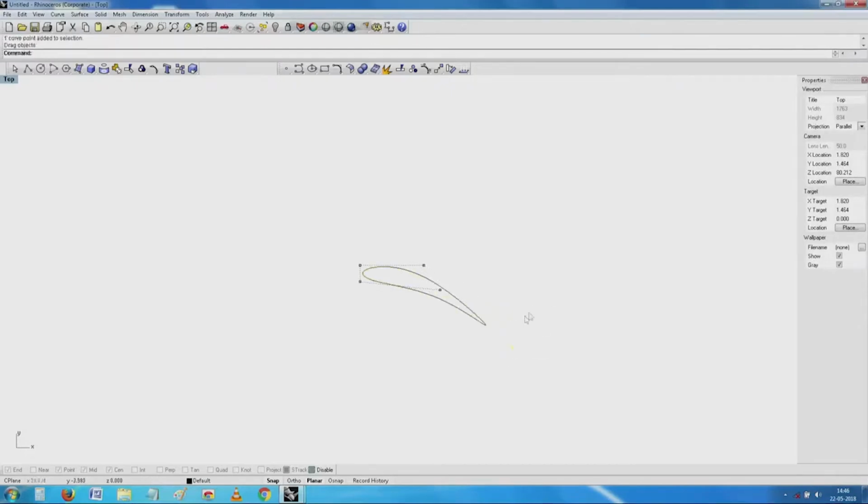rotation. This is how probably a cross section of the blade looks like. It looks like what is called a cambered aerofoil. Now comes the very important thing, why is it required? Why is this very peculiar shape given? When the air enters, typically it enters axially. When it leaves, because of this rotation, it has a tendency to also go at a slightly different angle. This of course I have unnecessarily made a little drastic.